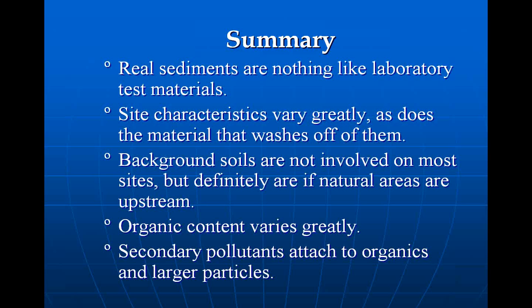I believe we need to do a lot more work to figure out where, if you go to a standard manual, let's just say in North Carolina, you'll find 4 or 5 or 6 practices rated at 85%. And the engineer can pick what he wants as long as he picks the right practice and builds it the right size, length to width or depth or surface of sand fields or whatever, he gets an 85. Well, those practices are not the same. I don't care that the number's the same. They are not the same. They don't work the same.